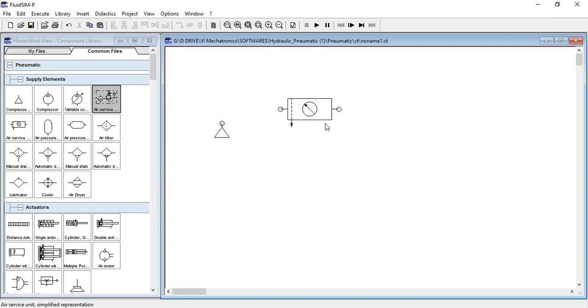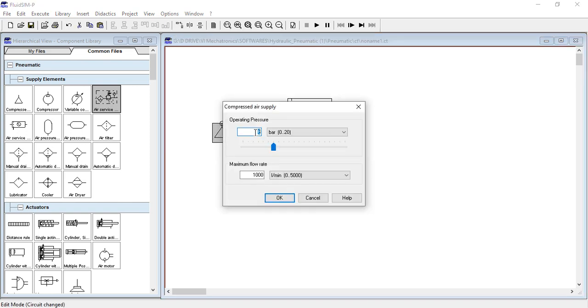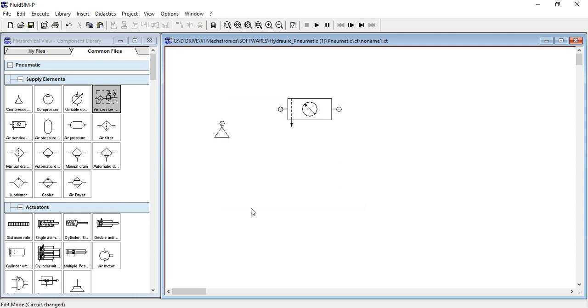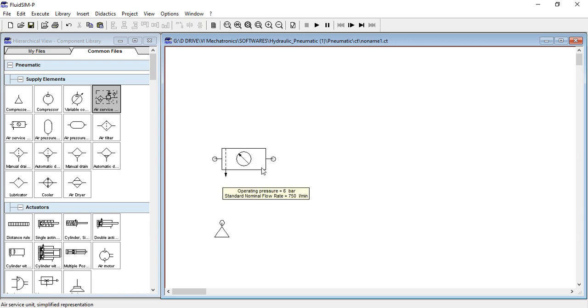Again, suppose this is the compressor. Suppose I set my compressor to 10 bar pressure. Okay, means there is a setup wherein my compressor is giving me 10 bar pressure, and there is a requirement that my circuit should have what pressure? 6 bar. So how to do that? Once the compressor is supplying air at 10 bar, we are able to regulate that in our regulator.